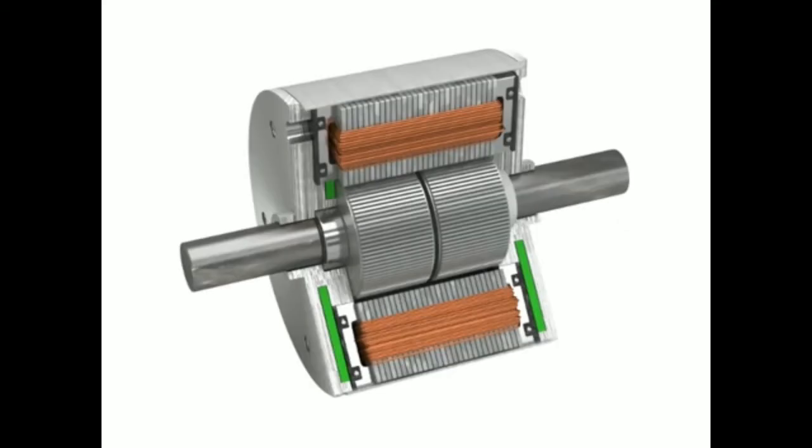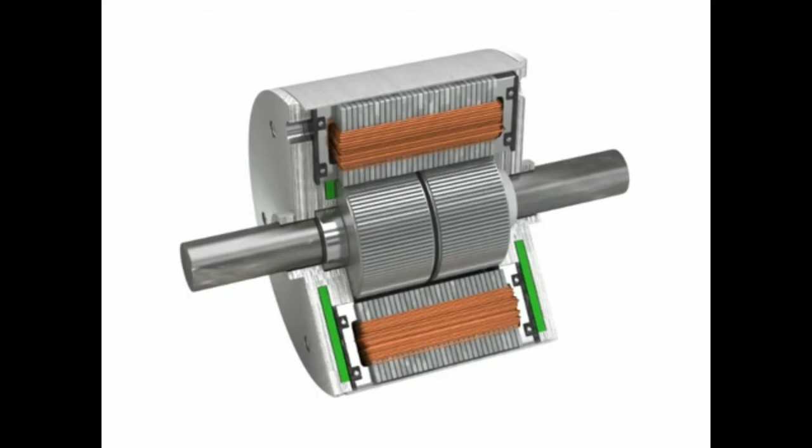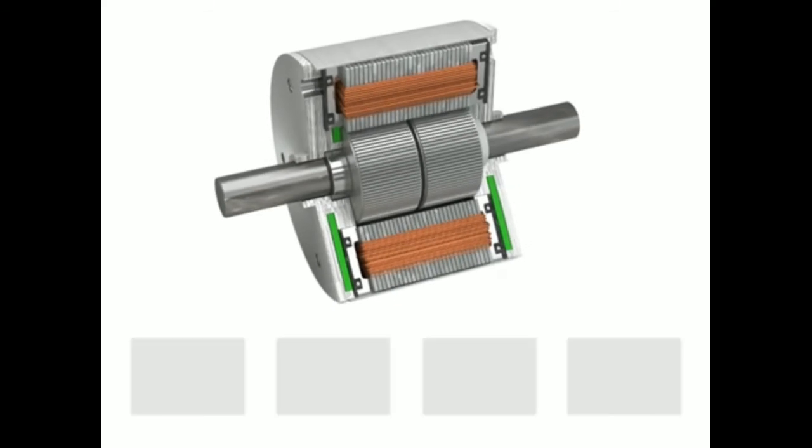With the DC brushless motor being the foundation of stepper motors, let's look at how the stepper works. Stepper motors are so named because each pulse of electricity turns the motor one step. A simple stepper motor system is comprised of four elements. The user interface allows the operator to input motion parameters such as speed, distance, and direction. Examples of an interface would be a programmable logic controller or data entry terminal.